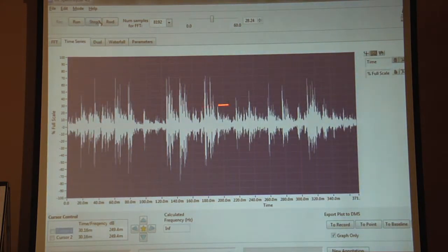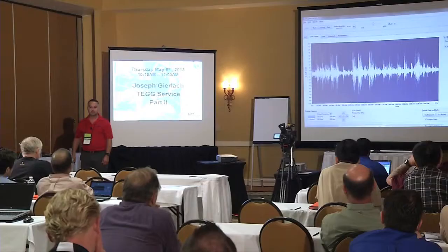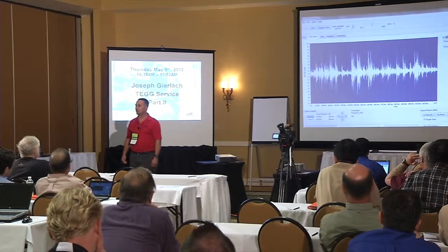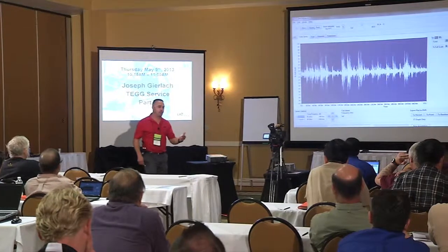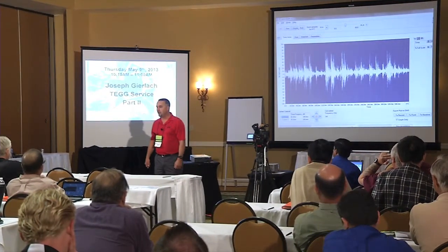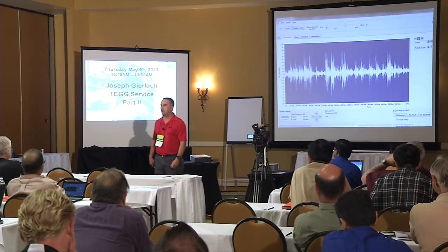I have a continuous event. I have variations in the amplitude of these excursions, and it sure as heck is not the same point in time, is it? What signature is that? That is tracking. So if you can become accustomed to looking for these footprints, you can be confident in your analysis. This tool doesn't lie.